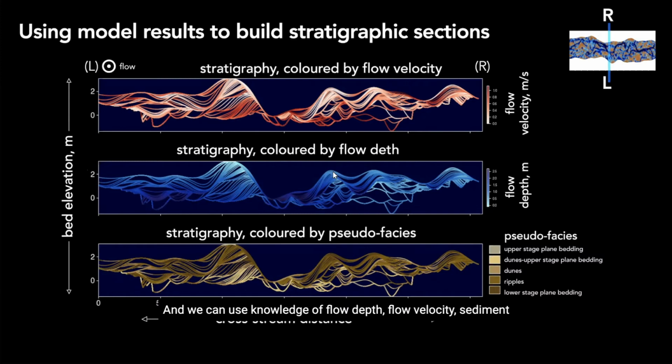And we can use knowledge of flow depth, flow velocity, sediment supply, and also shear stress conditions in the channel to reconstruct zones of bed form stability within the channel where we can predict where we would find particular bed forms in the channel. And we use these bed forms to produce what I'm referring to here as pseudofacies in the stratigraphy.